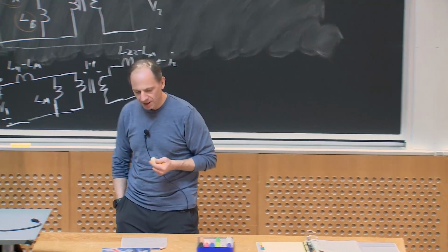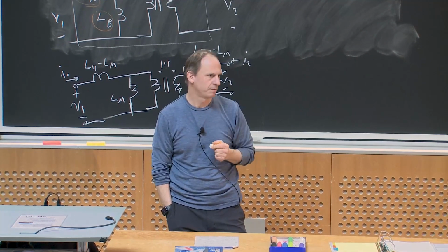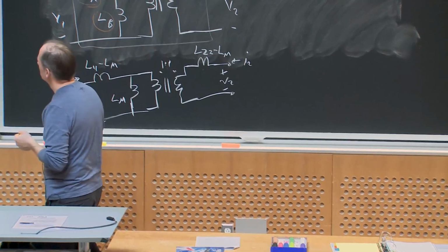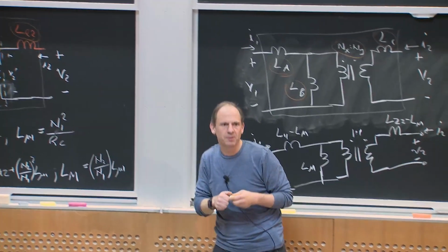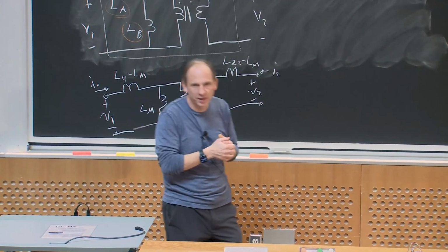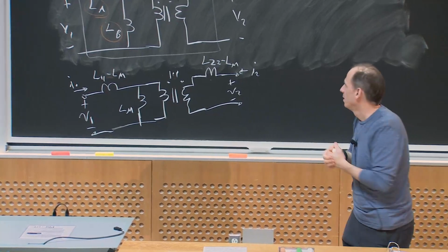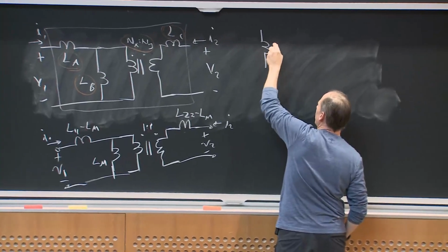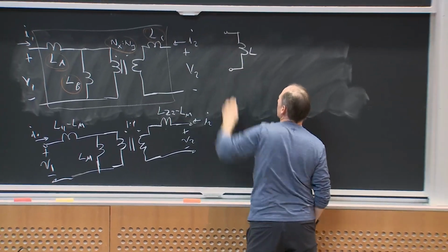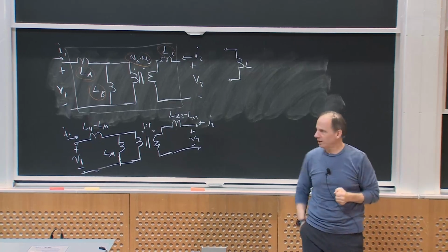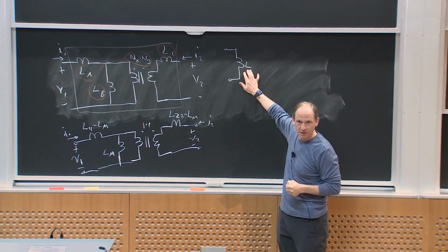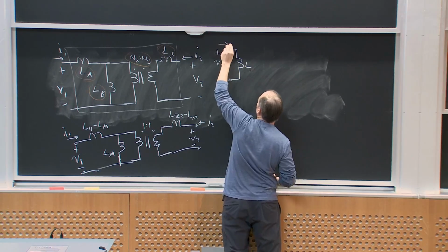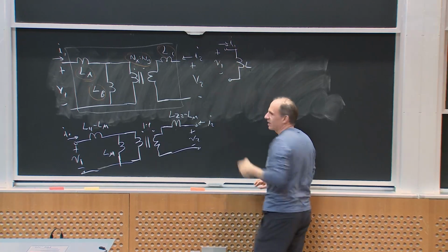So let's start talking about constraints on the parameters, right? I said I have 3 independent parameters, but can the parameters be anything I want? Well, no, they can't. Not for a real device anyways. Let's just start thinking about if I just handed you an inductor, L, right? You know, an off-the-shelf real inductor. What can I say about the inductance of this thing? Well, I would argue that in a real inductor, at least large signal-wise, the inductance has to be positive.